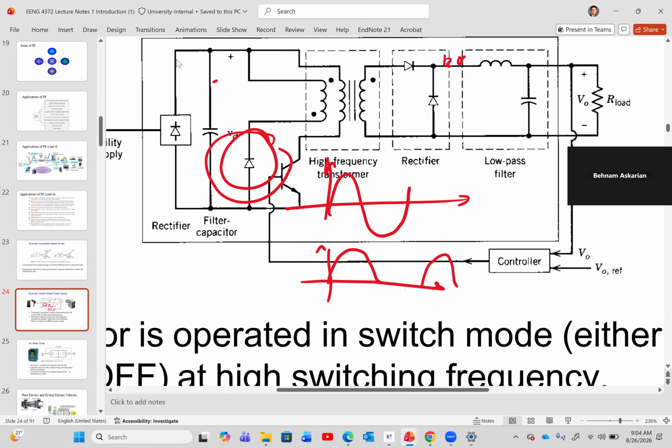And it's the same thing in a hair dryer. If you look at your hair dryer, it has different levels of heat or speed. You have high and low, okay? When you put it on high, the input is connected directly to the outlet. It's 120 volt. When you put it on low, it runs through a diode, and that diode cuts the signal in half. Now the heat that is generated is half. So by simply adding one diode, you can halve the power that goes into your hair dryer, half the heat, and half the fan speed as well.